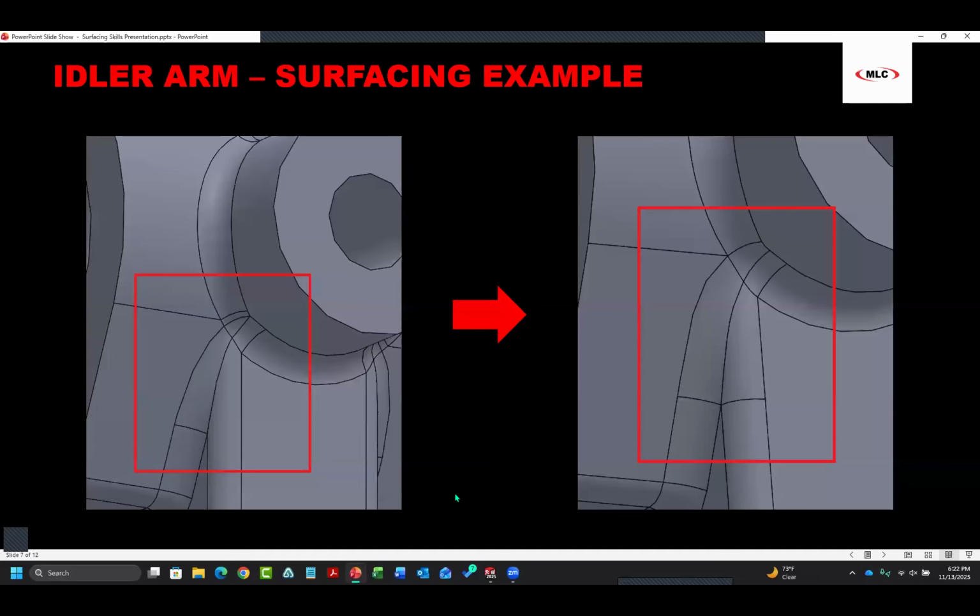So what we also covered in the first 2 examples is also common steps that you can use on STEP files, IGES files, Parasolid files, generic files. This is almost identical to what we call direct editing. So you are removing faces and replacing them. So everything we're doing here also applies to generic file types. Fillets are notoriously bad as far as how they're translated between CAD systems. That's not a SolidWorks thing, that's just a CAD file thing. They're algorithmically much different between CAD systems. So fixing fillets in imported files tends to be a somewhat common thing that happens.